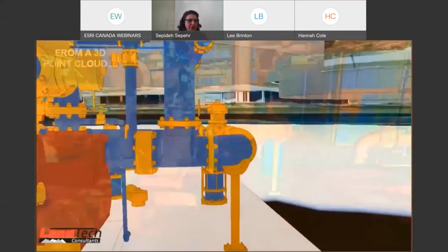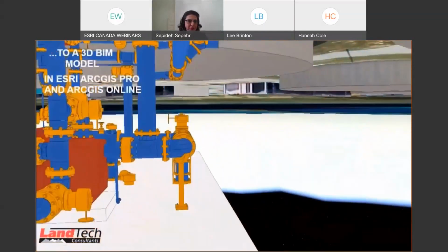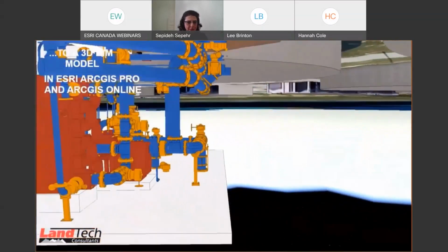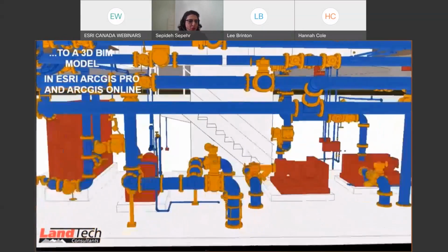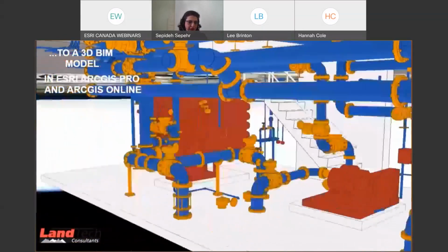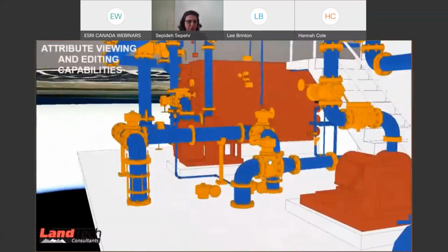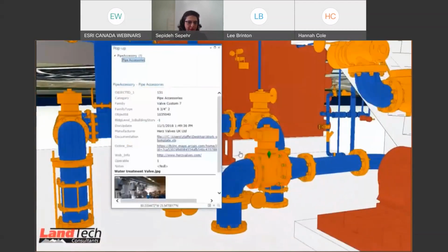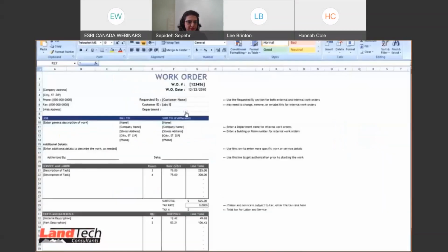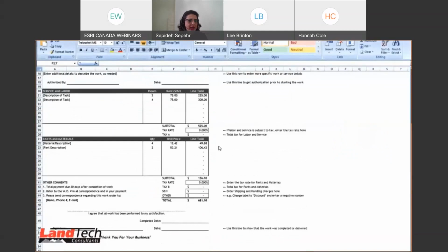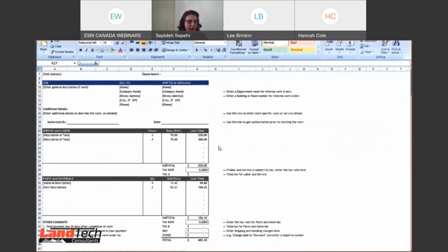The resulting 3D point cloud can be developed in the form of 3D building information in Autodesk Revit. Then the model can be converted to GIS 3D format in ArcGIS Pro. Hosting information on the cloud allows vendors to navigate and interact with the 3D model and its associated attributes in a web browser, mobile app, and dashboard.